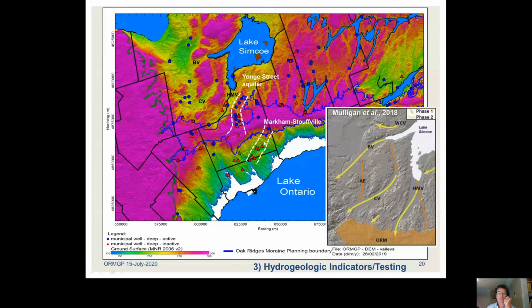The sewer came along here and they had a hard time controlling groundwater where the old Markham wells were. And what they had to do to control groundwater to allow construction, I think, is providing us some information that we need to adapt.